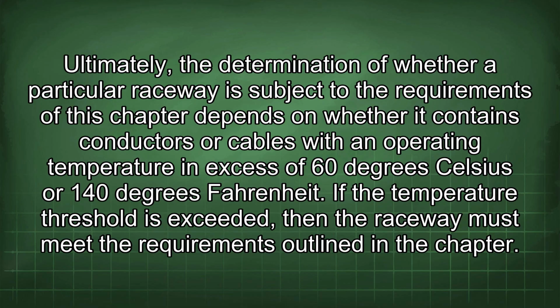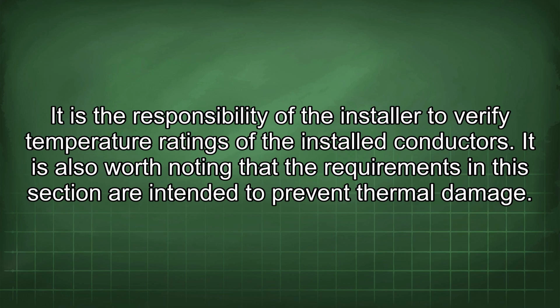Ultimately, the determination of whether a particular raceway is subject to the requirements of this chapter depends on whether it contains conductors or cables with an operating temperature in excess of 60 degrees Celsius or 140 degrees Fahrenheit. If the temperature threshold is exceeded, then the raceway must meet the requirements outlined in the chapter. It is the responsibility of the installer to verify temperature ratings of the installed conductors.